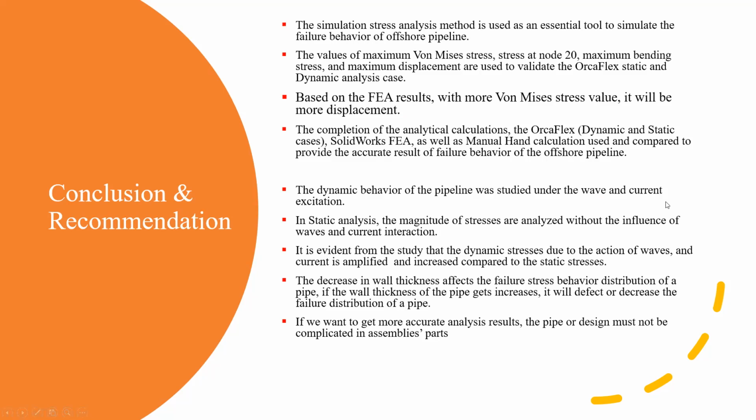We know in OrcaFlex, I used two cases, a dynamic and a static case. The difference is the dynamic behavior of the pipeline was studied under wave and current excitation. However, in a static case, all the stress analyses are done without the influence of waves and current interaction. It is evident from the study that dynamic stress due to the action of waves and current is amplified and increased compared to the static stresses.